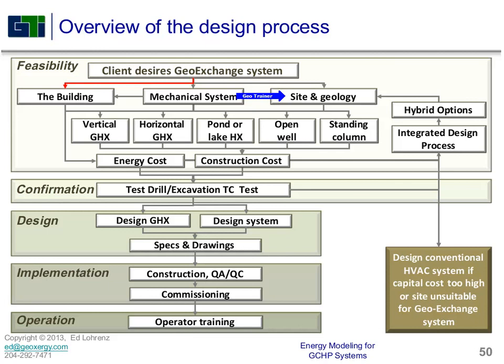But at the end of the day, it boils down to what it's going to cost to build the system. If putting in 2 U-tubes is going to add $3 a foot to the cost of building a system, it might be better to put in a single U-tube and do a bit more drilling. But you've got to talk to the contractors that are going to be putting these systems in. A lot of guys aren't going to like putting 2 U-tubes into a borehole. There's a bunch of things you need to look at.